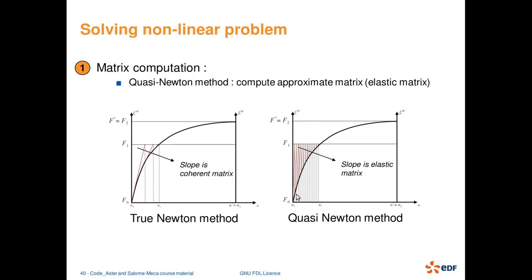Now this method is useful when the system is very nonlinear, and when the computed tangent matrix becomes singular. If the matrix becomes singular, that means the derivative is not finite, it becomes almost zero, so I cannot apply the Taylor series approximation, and therefore I cannot get the next solution.